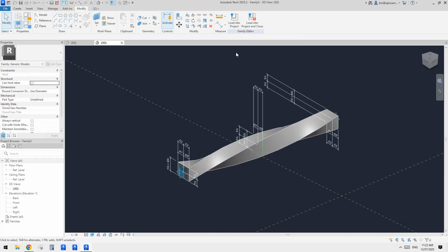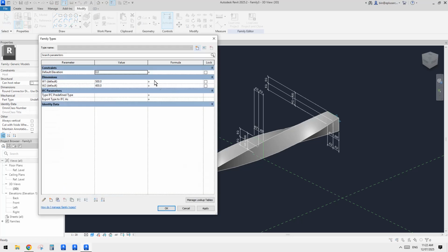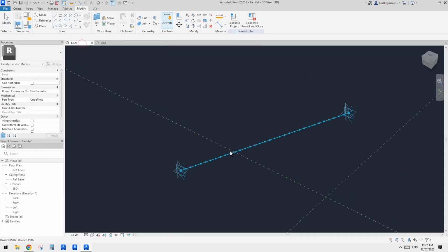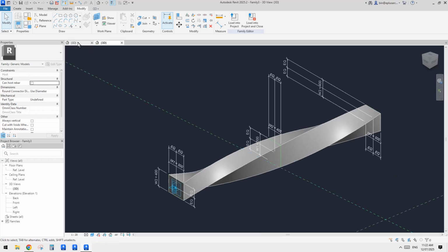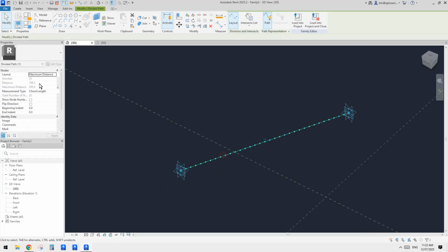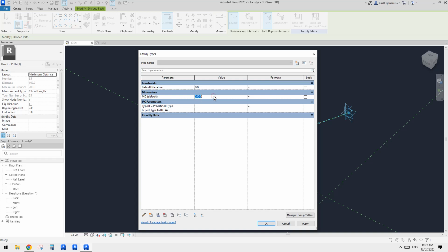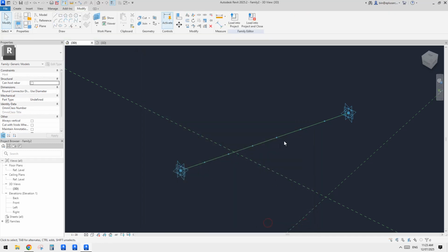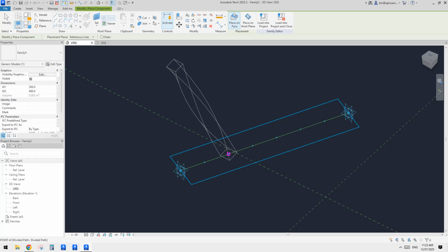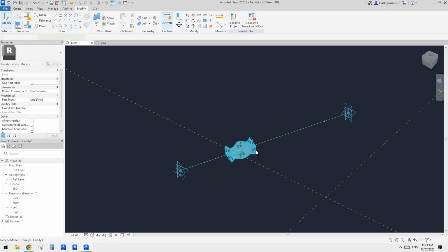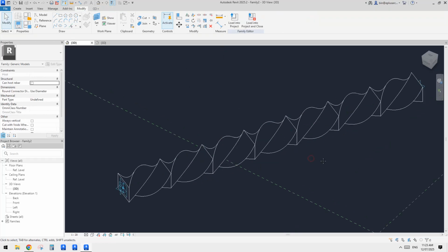Actually, I'm going to change it, 500 is quite big relative to this spacing of 200, so it's very small, right? So we can either just increase the spacing here or just reduce the size of the profile. So I'm going to just type, change this one to 1 meter. So yeah, it's not too many. So I load this one in here, and then I'll just place here 1, 2. So now if I click on repeat, you will see